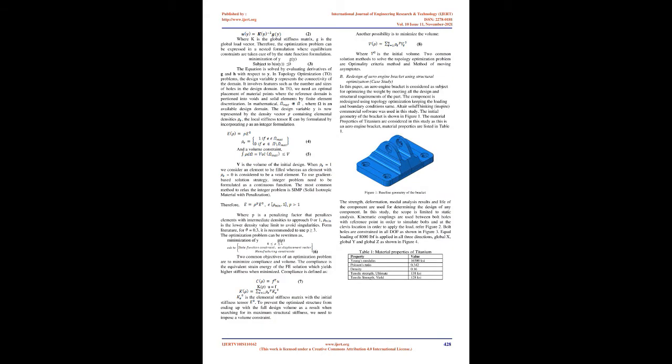With the new manufacturing machines allowing the use of metal powders in additive manufacturing, metal parts with complex geometries can be manufactured. The conventional process of casting followed by machining needs the part to be designed to avoid any kind of casting defects like cracks, pores, discontinuities, etc. Then the critical features need to be identified and machined in order to obtain good surface finish, adding to the cost of the part.